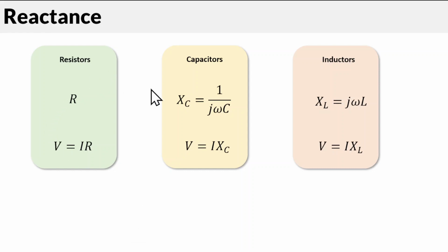So we've got these three relationships for resistors, capacitors, and inductors that allow us to use Ohm's law in a particular way for capacitors and inductors as well as resistors. It also opens the way, through the use of imaginary numbers, to look at the way these components introduce phase changes into signals. That will become very important in a couple of applications down the line. So let's see what effect this has on more interesting circuits than just a single component.